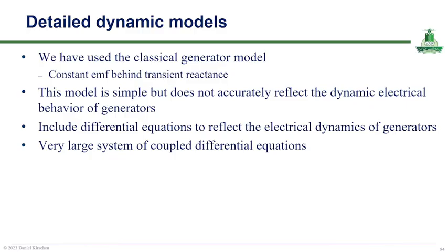So in reality, generator behavior is influenced by complex electromagnetic interactions within the rotor and stator circuits. To model these effects more accurately, detailed dynamic models include additional differential equations that describe the electrical dynamics of field windings, damper windings, excitation systems, and other machine components.